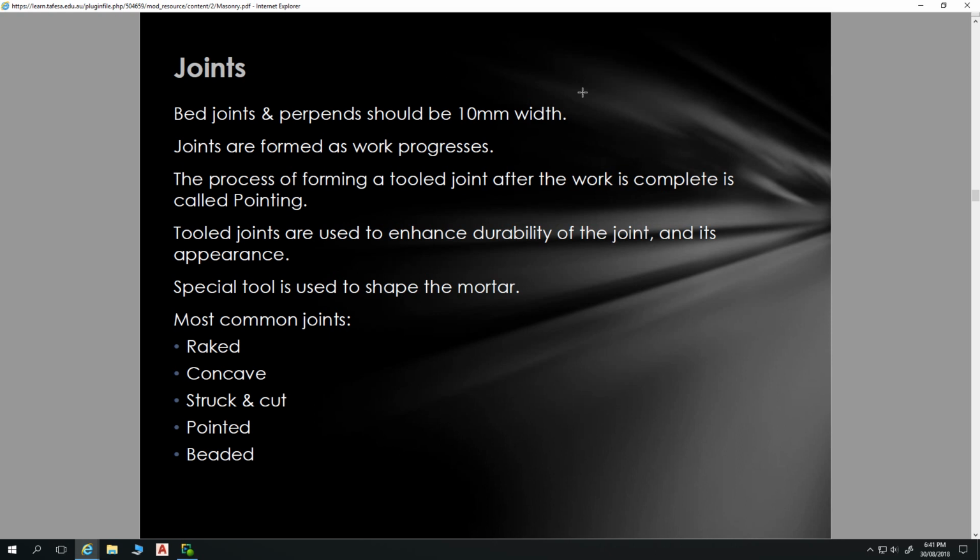If you don't, then your bricklayers just have to be cutting lots of bricks, and you get bricks that are in thirds and quarters and so on, and it just doesn't look very good either. Bricklayers only like to cut bricks in half, and that's it. And so when you get to a door opening, you'll have full bricks and then half bricks, because you've got that stretcher bond of them overlapping.